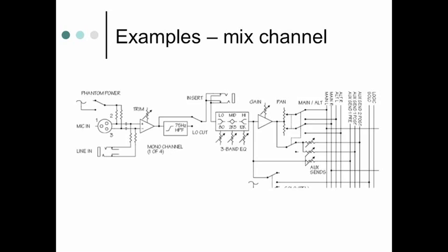Do you see here after you EQ, you've got a gain control with a variable resistor, right? Right here. See it? So that's how loud your microphone, if you plugged a mic in, is going to be. So your trim here at the front end is your microphone level preamp. Then here is your gain, your output level of how loud it's going to be going to your PA. It is the fader. The trim knob on a real board, the trim knob up top, is the microphone level, and then the fader is the gain as to how much comes out of that path.